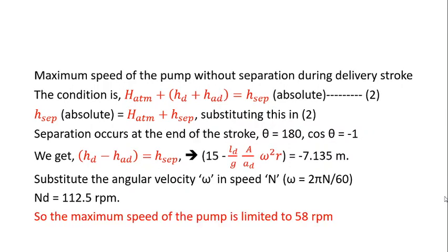Similarly, if you consider the delivery stroke, then the separation occurs at the end of the delivery stroke. At the end of the delivery stroke, the acceleration head or retardation head, theta is 180 degree. So cos theta is equal to minus 1. So it will be negative.